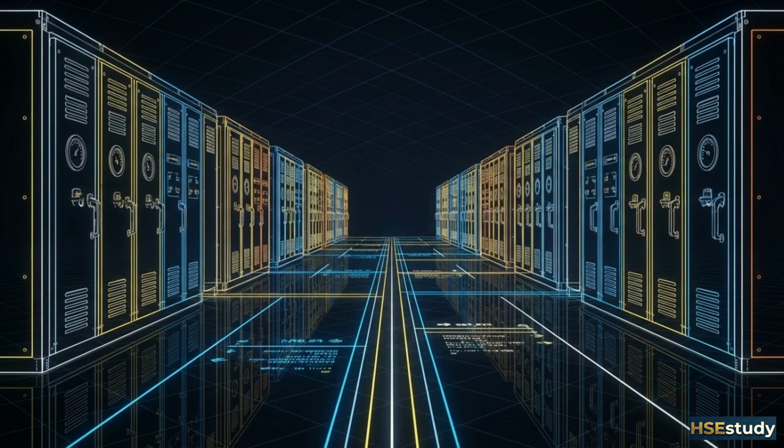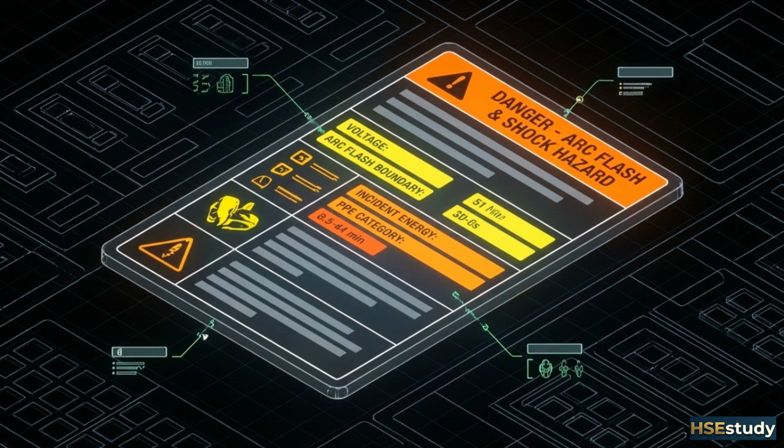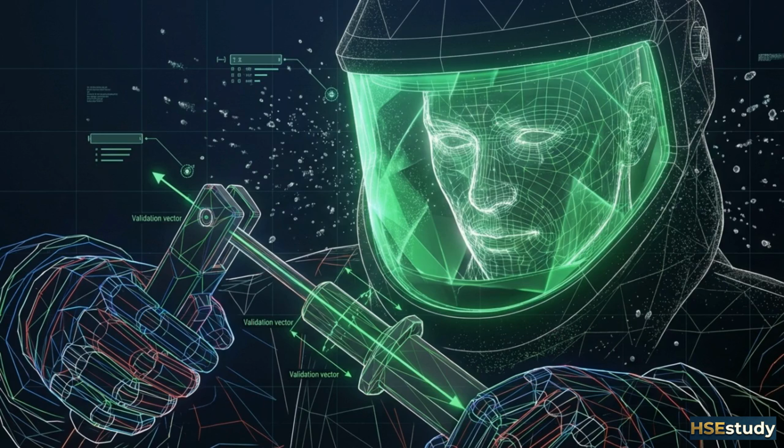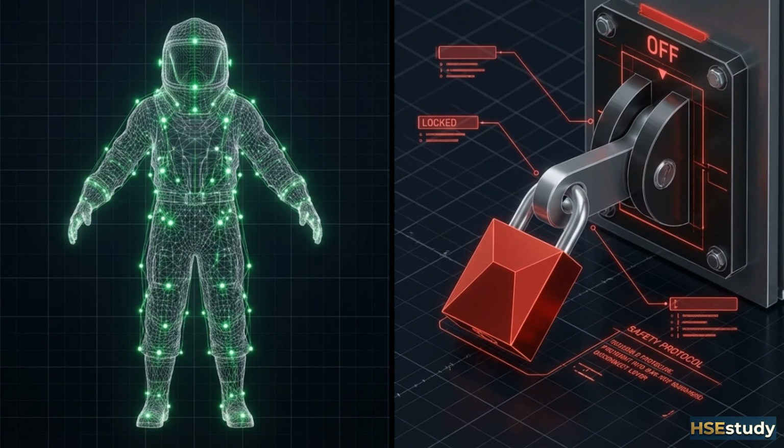All of this abstract engineering software ultimately translates back to the physical reality of the switchgear on the facility floor. The final deliverable of that modeling is the data printed on an NFPA 70E arc flash hazard warning label. A technician reads this label to determine the exact level of arc-rated personal protective equipment, or PPE, required to survive a blast while working on that specific panel. PPE is the last line of defense. The true goal is to establish an electrically safe work condition.